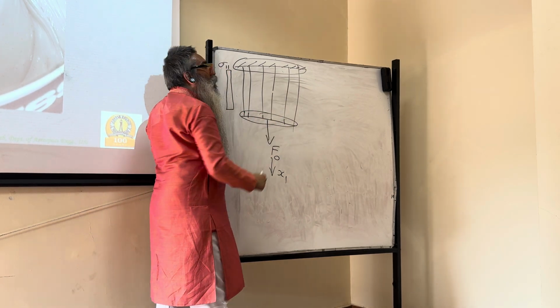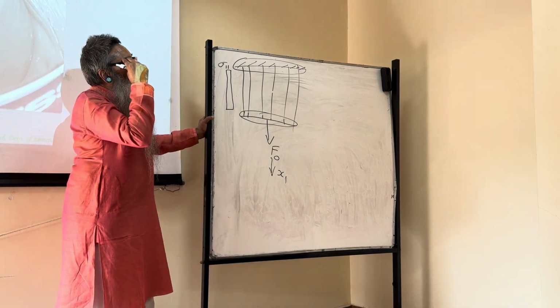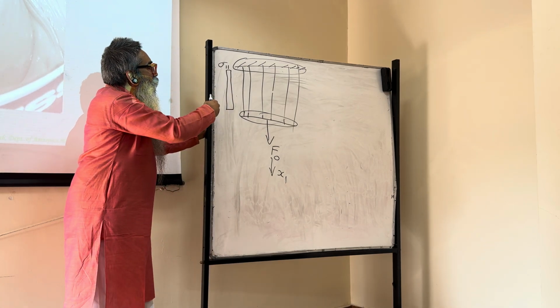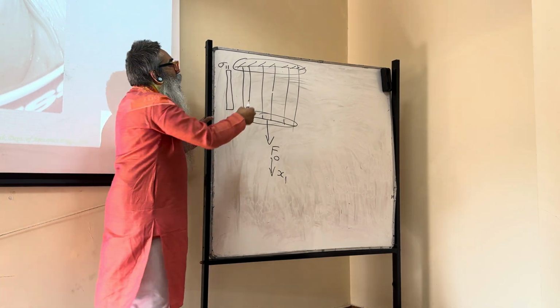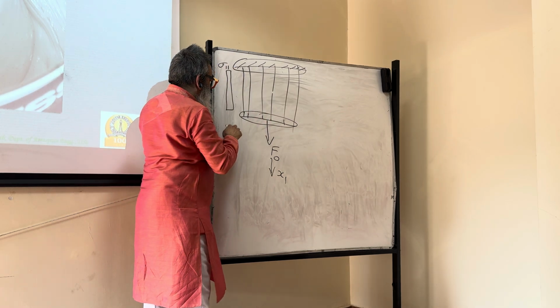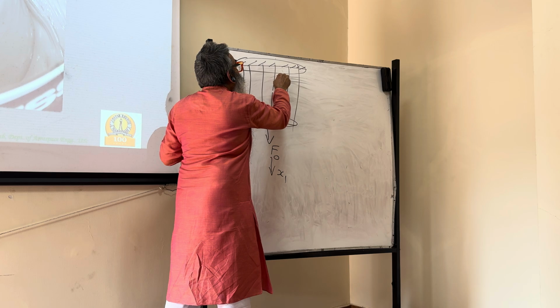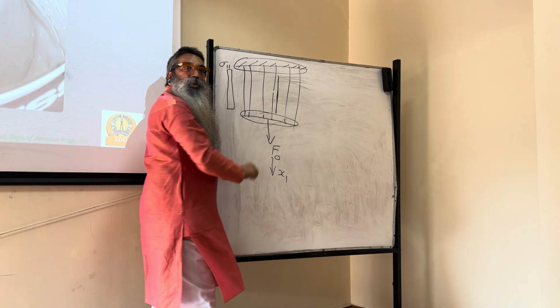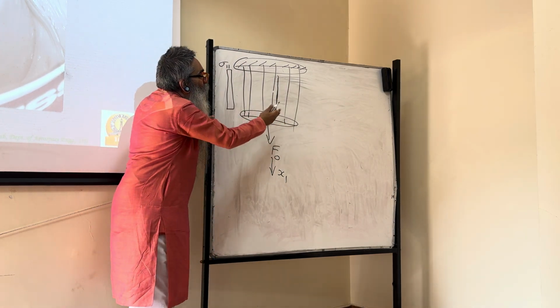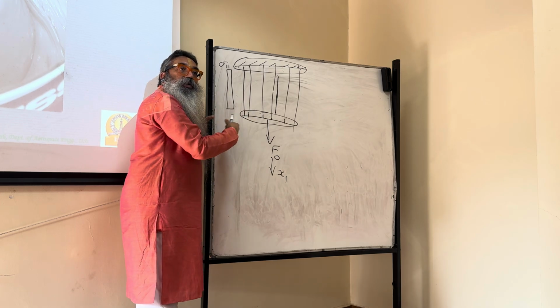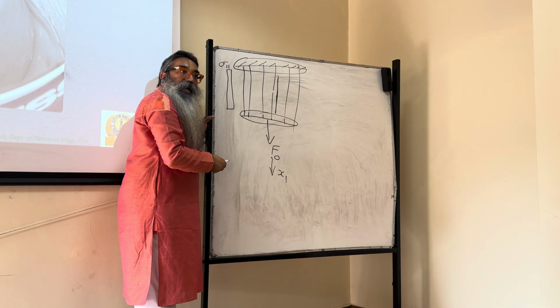Now on the broken fiber, if the matrix were not there, then the stress in that fiber alone just comes to 0, right? So it's just 0 over there throughout, which means the other fibers have to take all of that load redistributed, which is why it failed first.